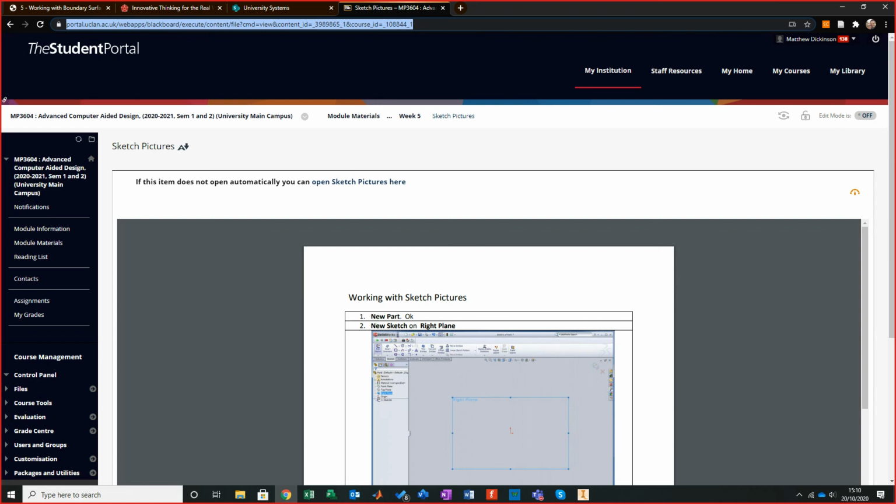Like for us, when we've been doing the skeleton, what we've been doing is using heights of the average 90 percentile, and then we've been putting that into a stick drawing actually on our CAD system that we're using. Actually, the CAD system we're using for that is Inventor. And then with that, what we do is we essentially use that as a master sketch, and then we draw around that to make sure that our proportion remains in good perspective.